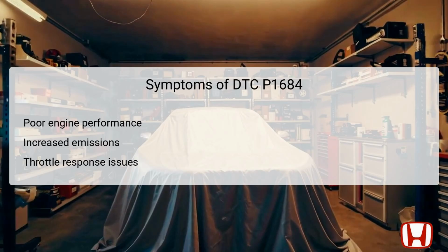One of the most common symptoms is diminished engine performance. Drivers may notice a lack of power during acceleration. Moreover, increased emissions may also be a consequence, as the incorrect air-fuel mixture results in higher levels of pollutants being expelled. Throttle response issues can be notable.